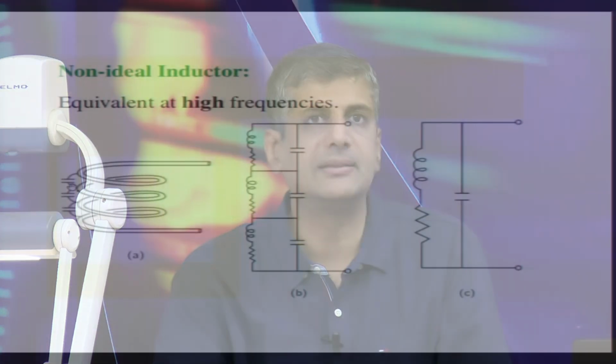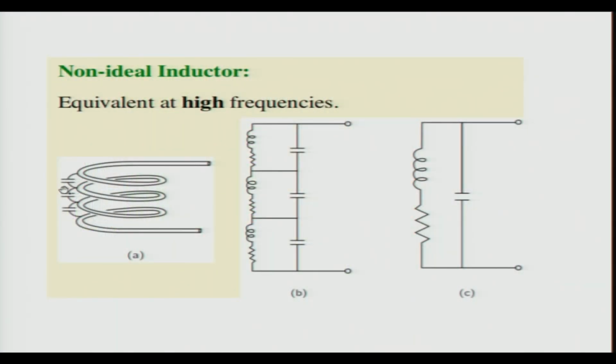And if that happens, that may make the transformer a bit vulnerable, because once the coils shift with respect to each other, they may cause abrasion of the insulation between the windings, and that may actually cause current flow between the windings, like what we show as capacitors here in this diagram. You may also have a resistive effect there, that is some current may start flowing from one turn to another turn, that is called a turn fault, and that may damage the transformer.